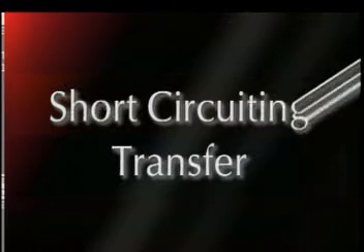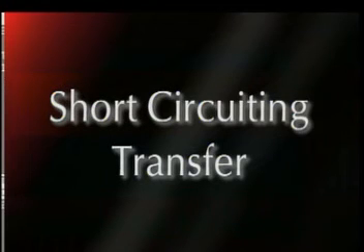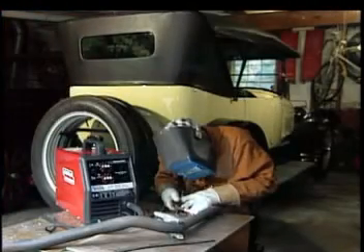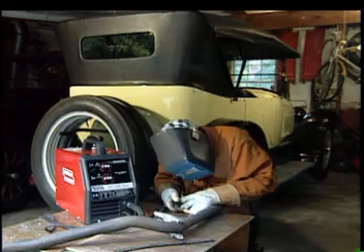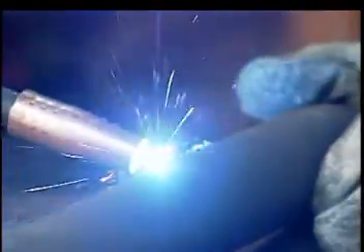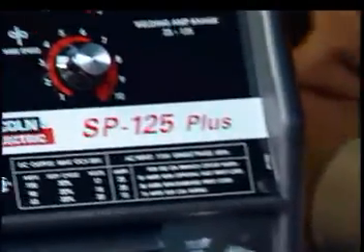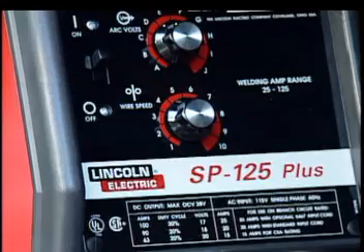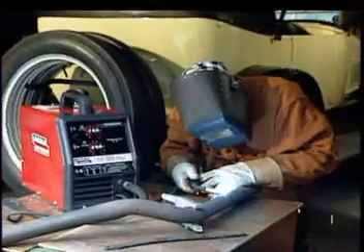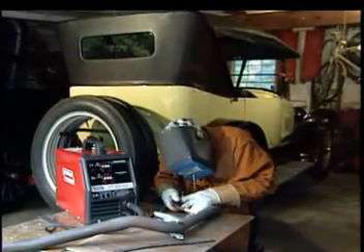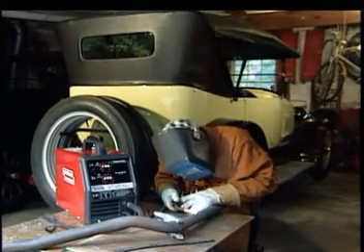Let's look at the characteristics of the 5 major metal transfer processes in greater detail, starting with short-circuiting transfer. Short arc has the lowest heat input, making it a very fast-follow process. The weld puddle freezes quickly to allow efficient out-of-position welding. Equipment for this process is relatively inexpensive, but the short-circuit process produces some spatter, has low deposition rates, and lack of fusion is not uncommon.